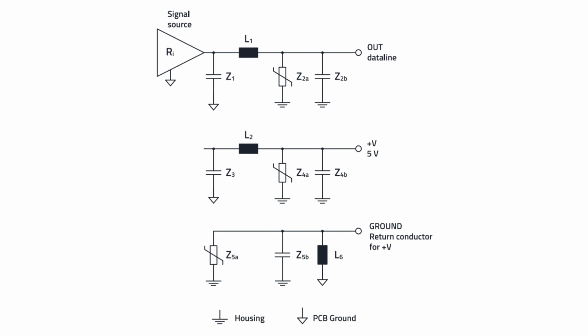A digital square wave signal with an amplitude of 5 volts and a frequency of 5 megahertz on the data line is what we're going to look at first. Now, the standard value of 90 ohms is assumed for the impedance of long data signal lines, and there's a voltage of 5 volts DC at 2 amps on the supply voltage line.